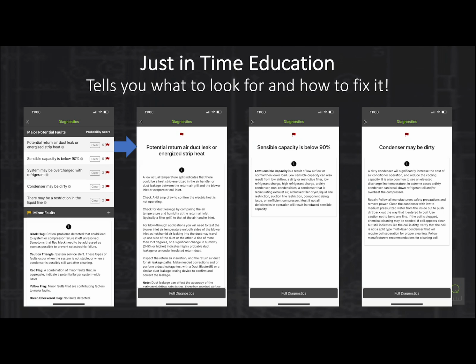Just-in-time education: we talked about tapping on the faults. In this case, measureQuick is picking up a potential return air duct leak, right? There are 5 symptoms of that. It might be things like high suction pressure, high head pressure, or high superheat. But there are 5 things that are typical when we have a return air duct leak. Low capacity is a typical thing we see. So it's going to tell you what that means, and that the low temperature split indicates there could be a return air duct leak problem, what you need to check, and how to do that process.